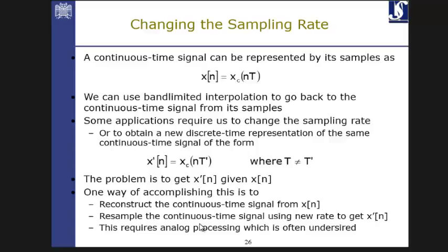Yes, please. Can you also take the average? Here, downsampling is somehow the averaging. No, we're just ignoring. Because the downsampling factor is 2, every other sample after the first sample should be cancelled. So we are ignoring this one, this one, this one, and so on. If it was 3, then we keep this one, these 2 are ignored, we keep this one, these 2 are ignored, we keep this one, and so on.